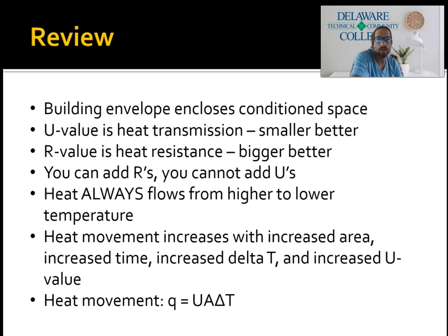This is an identical slide from before. Remember, we're dealing a lot with the building envelope, which is the area of a building that encloses the conditioned space. So it's usually where the insulation is, but it also could be where the floor is. It's not always easy, but just remember that's really what we're concerned with, because all of the space inside of the envelope is the area that we're actively heating and cooling, and so that's what we'll use to calculate our heating load and cooling load when we get to that.